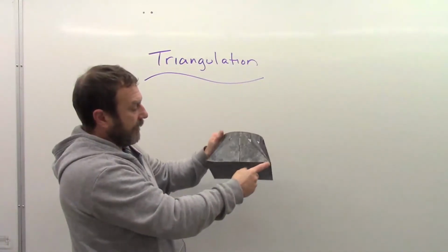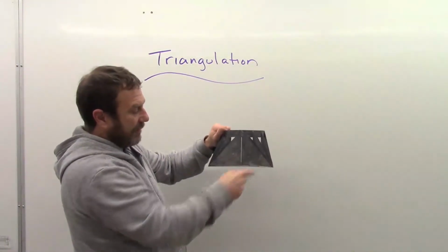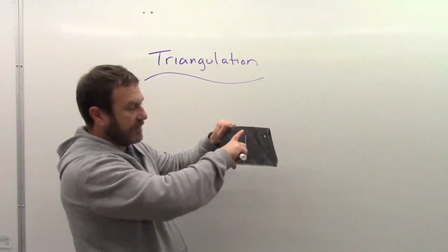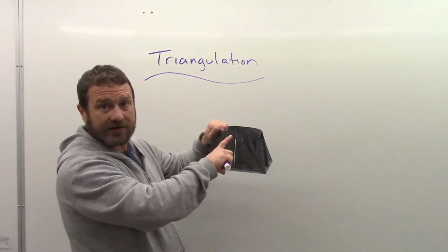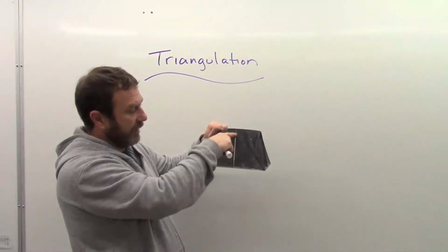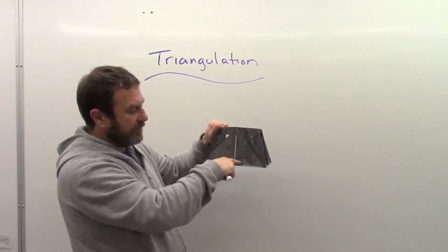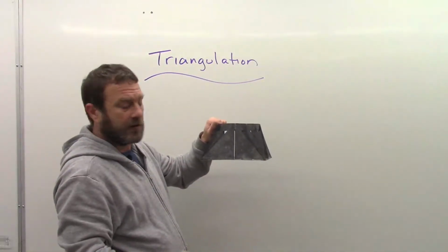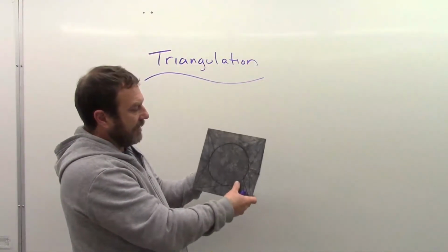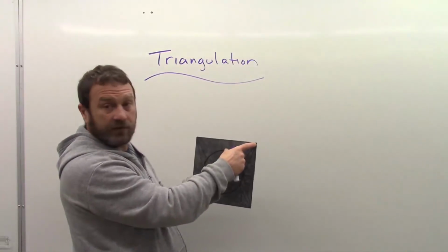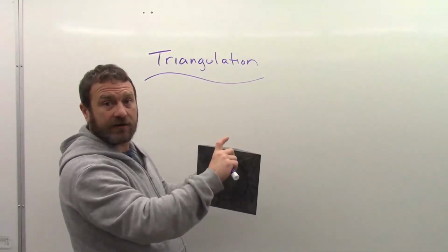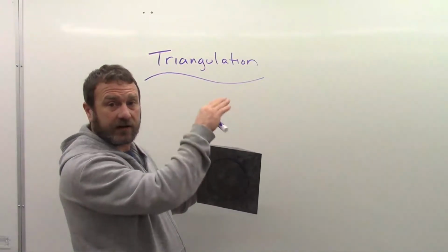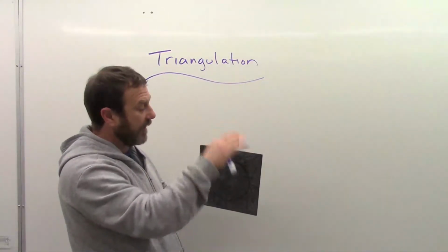If we take that base length and put it 90 degrees to the vertical height, because that's the second leg of our triangle, this vertical here, if we put those two at 90 degrees, we get the hypotenuse. So what that tells us is that any element line in the plan view, put 90 degrees to the vertical height, we can create the hypotenuse. We can find the hypotenuse.